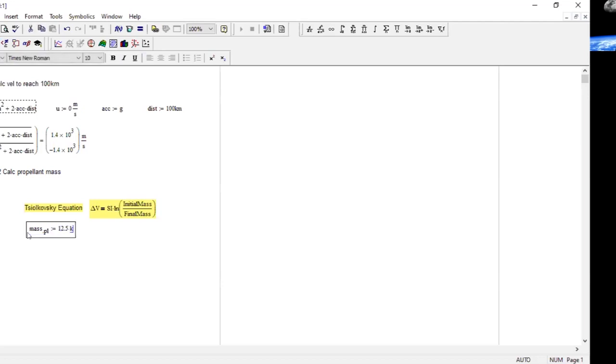Mark originally asked me to look at this with a payload of between 10 and 15 kilos, and so we went for 12.5. Other bits and pieces that I haven't thought about, there's always extra bits that you don't think about: glue, fixings, bolts, rivets, the rest of it. I'm going to call these extras, and I'm going to give that 2 kilos.